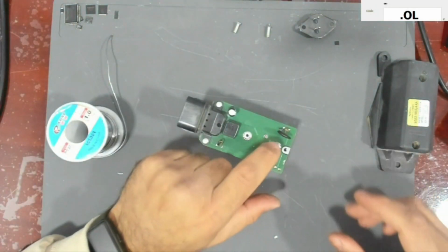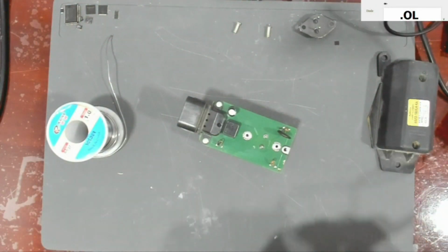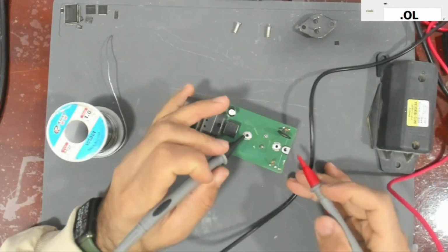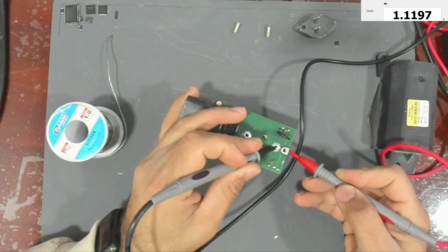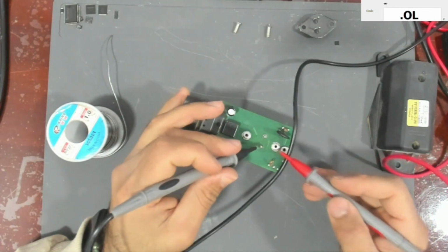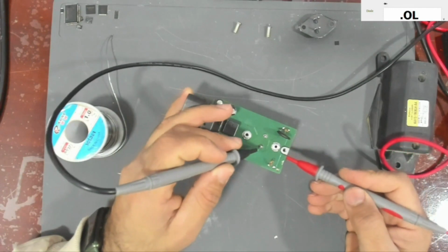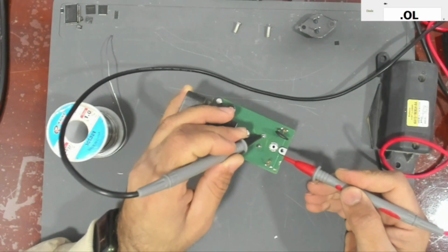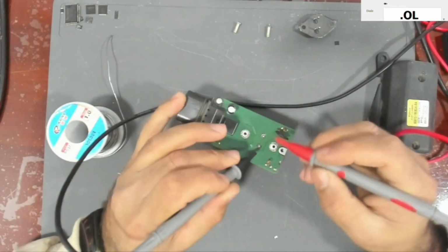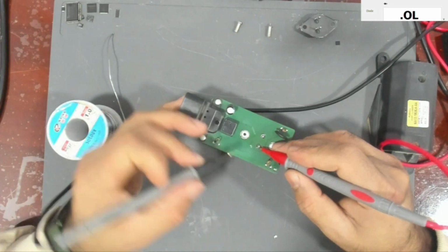Okay, so let's test these two with the heatsink, if they make contact or not. So this one and this one, and they should not make any contact with these, but they may read in diode mode. So let's try this one. It does not. This one does not. So let's try to reverse these two probes.